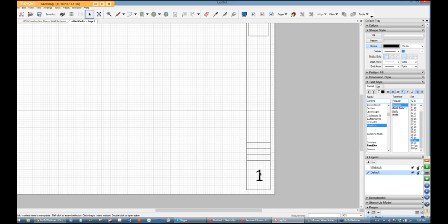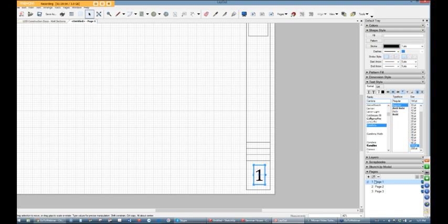Okay, so that is not on, I hope, if I got this right, not on every page. If it were, let's make that on every page, just to move that to that other layer. Right click, move to layer title block, I guess. I go to other pages, you can see it always says 1. So I changed it here, double click on it, change it there to 3. If I go back to other pages, it's still going to be 3.